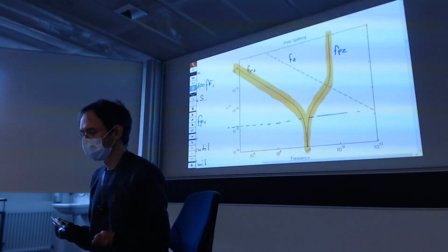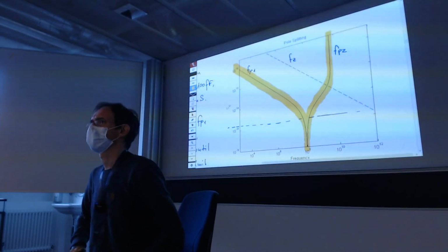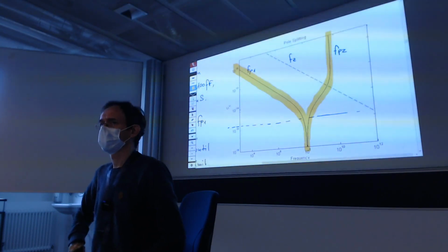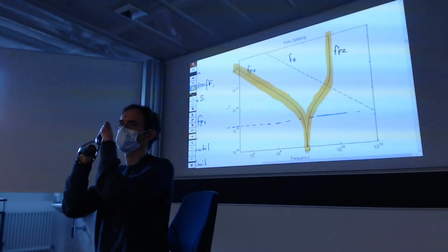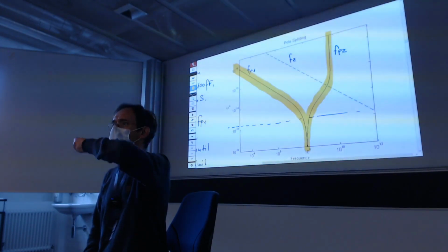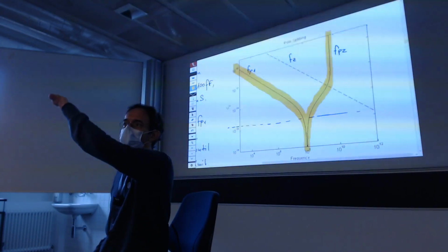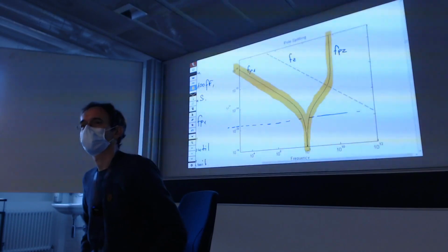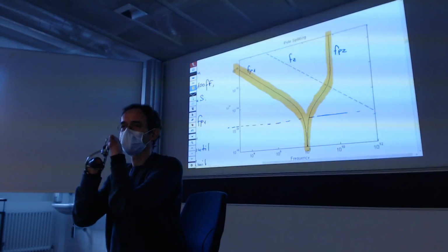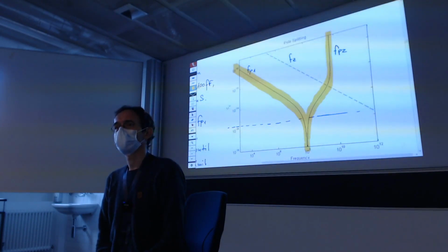Now, if you remember your feedback theory, like phase margin from stability theory, you will remember that if you have two poles close together at the same point, this will cause an immediate phase change of 180 degrees. So you will get from 0 degrees phase to 180 degrees phase. So if two poles of an amplifier are very close together, you will lose all of your phase margin, and it is not going to be stable.